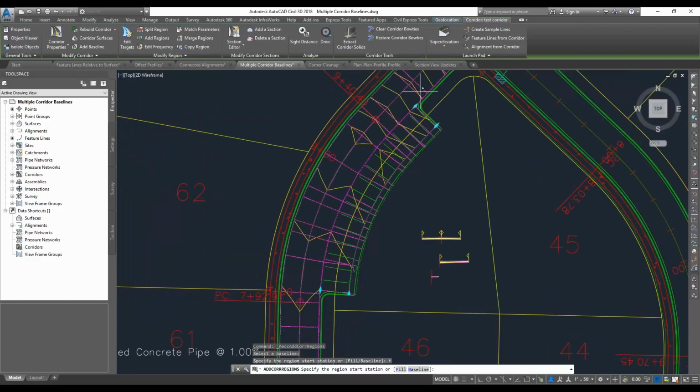So you might say, well, I could have just split the region in this mainline corridor and then had another assembly with the parking lane and the sidewalk attached to it. That's true, but one of the nice things about this is, let's just say we decided our parking lane is a little bit smaller. Just grab that. Maybe the sidewalk's not through the whole parking lane, and it's just really quick design changes in that way without having to mess with a bigger assembly. So not the only use case, but just one use case for this is with the roadway and the parking lane like that. Really nice feature. And remember, these are all dynamically linked feature lines that we're building off of.